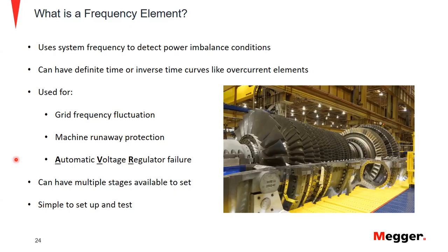So it's operating above synchronous speeds. So we can have an over frequency situation, or we can also have an under frequency situation. And this will bring the generator out of sync as well. So we definitely don't want to damage the turbine, since the generator is the main piece of the system that keeps everything going.